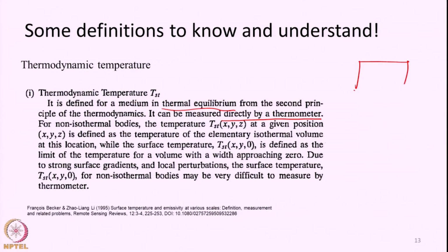Let us say there is a water tank. Someone asks us to measure the temperature of water in the tank. If we take a thermometer and measure just at one particular point within the water tank, it may not be representative. The temperature at different points of the tank may vary. Normally, we will take at least 4 or 5 different measurements, take the average out of it and present it.